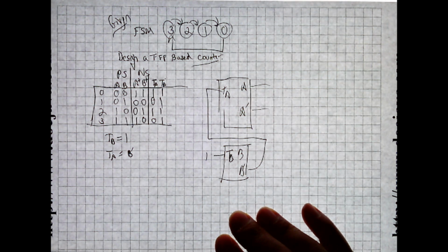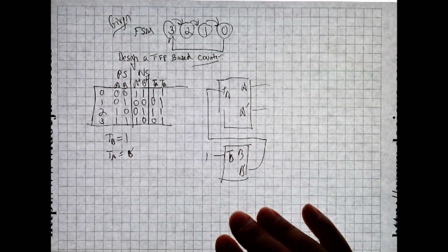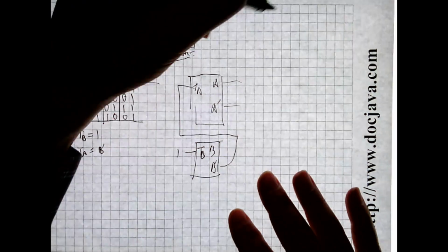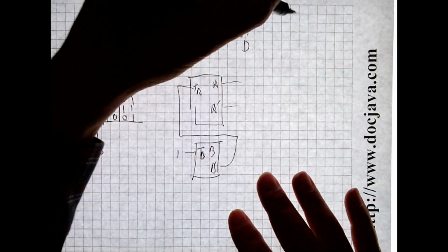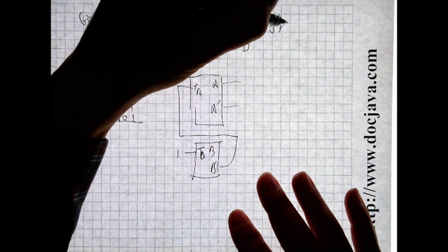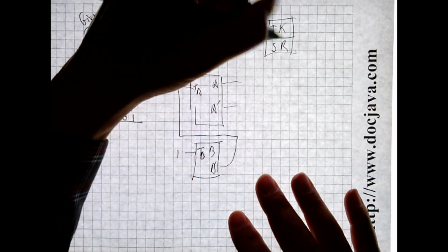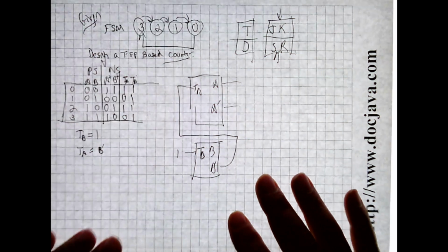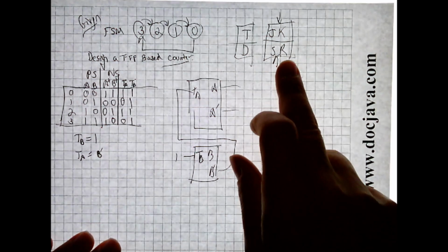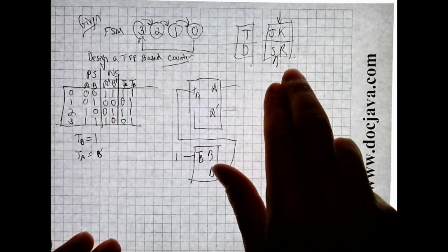Is everybody kind of following along on this? Is it making any kind of sense? So what have we seen so far today? We saw toggle flip-flops, and we saw D flip-flops. Other flip-flops include JK flip-flops and SR flip-flops. But these flip-flops have 2 inputs instead of 1, so they're rather more complicated to design with, although they're no more complicated to implement, and sometimes the implementations are even simpler.